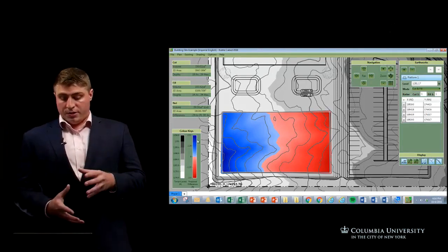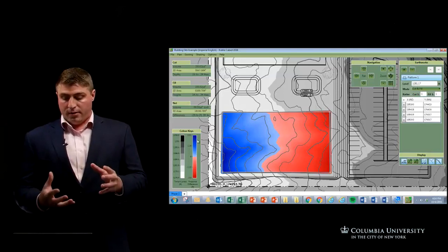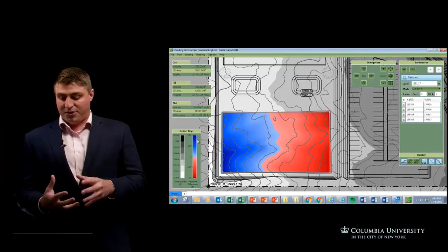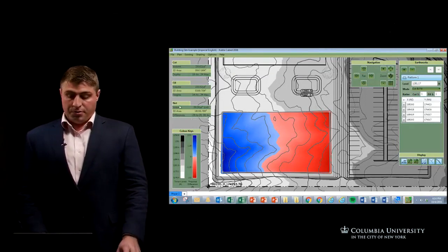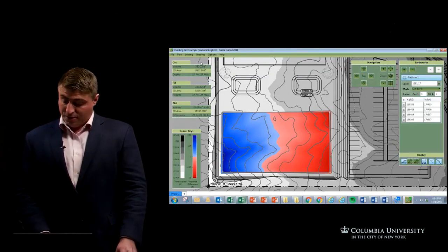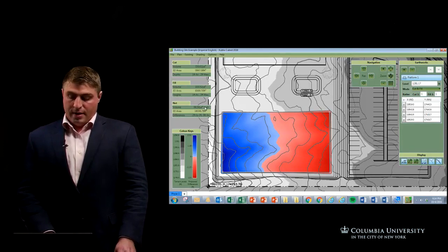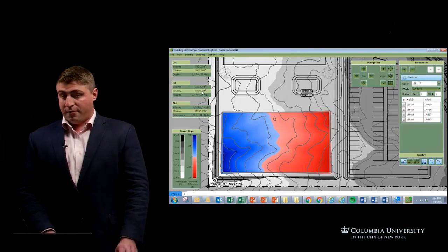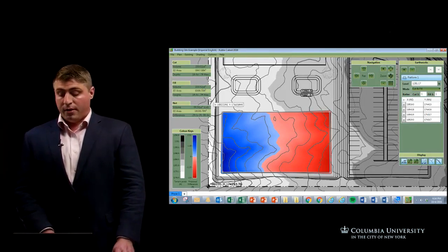All of these quantities will be built into your estimate in order to properly capture all of the pricing data. You will need to account for the 330 cubic yards of cut area and the net 100 cubic yards of excess that will need to be transported off-site. Finally, you will need to quantify the equipment rental costs and the operating costs of that equipment for both of those operations.